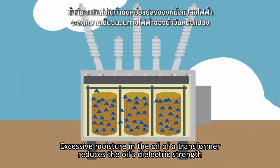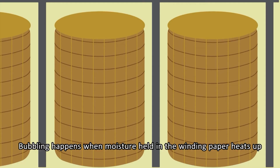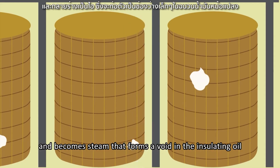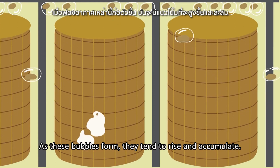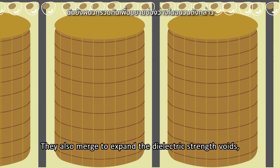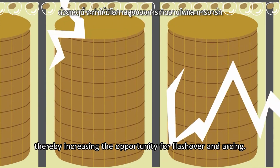Excessive moisture in the oil of a transformer reduces the oil's dielectric strength and introduces the opportunity for flashover and arcing. Bubbling happens when moisture held in the winding paper heats up and becomes steam that forms a void in the insulating oil. These voids have lesser dielectric strength than insulating oil. As these bubbles form, they tend to rise and accumulate. They also merge to expand the voids, thereby increasing the opportunity for flashover and arcing.